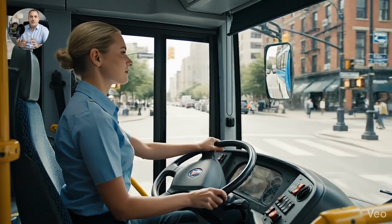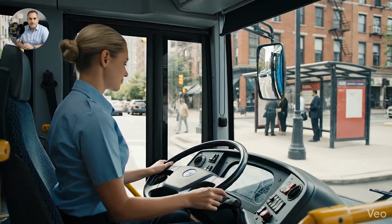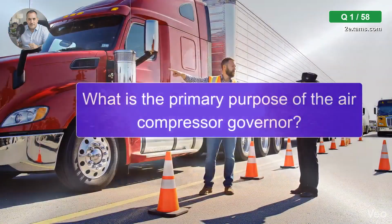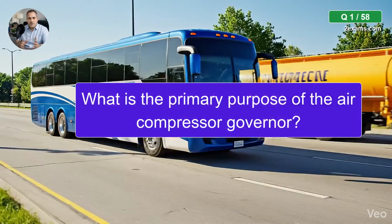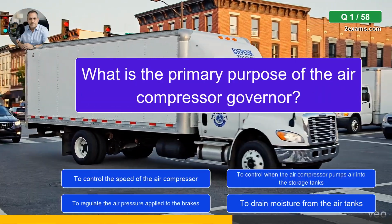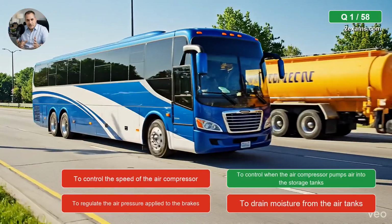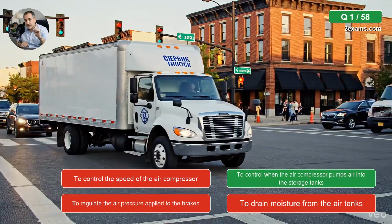Here are the 60 questions for the US CDL Air Brakes test. What is the primary purpose of the air compressor governor? The correct answer is to control when the air compressor pumps air into the storage tanks.